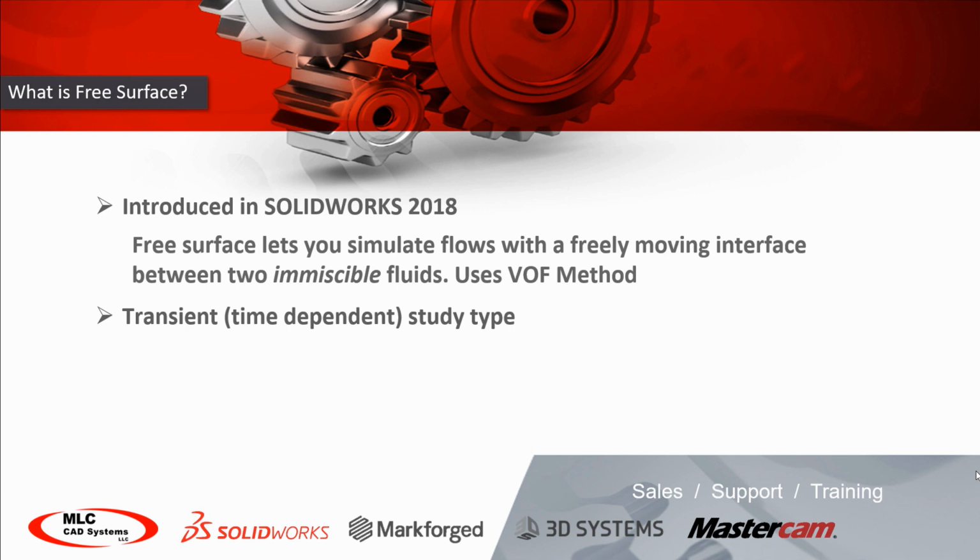These are going to be transient, or time-dependent, studies. So I mentioned I'm doing this in 2D. When you get into fluid simulations, solve time can take a bit longer. Now, Flow Simulation will use all of the computer you give it, so if you're hyper-threading or have multiple CPUs, it will certainly use all of that. But keep in mind, transient studies, or studies that take place over time, can take a little longer to solve and be a little bit more computationally intensive than your general steady-state setups.